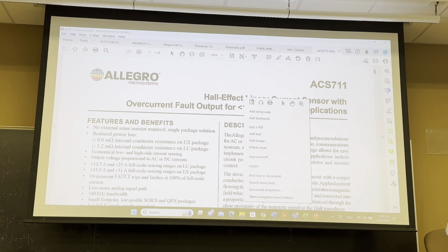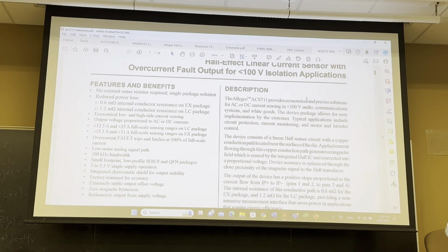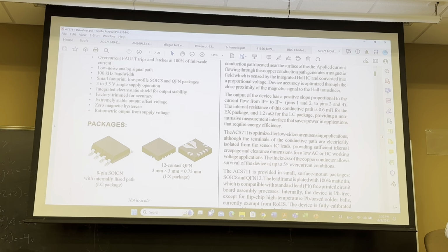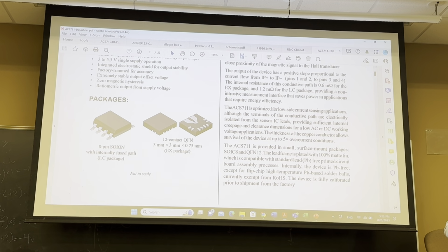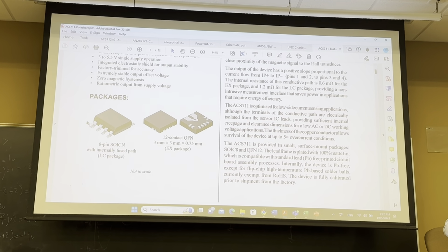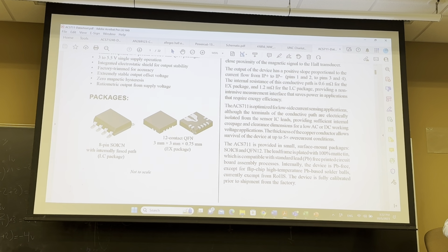So it's Hall effect, plus or minus 5%, doesn't matter, so we come here. Sometimes it says what the typical application is, and that may help you. It comes in two different packages, so now you want to see which one you want to use. This one is a SOIC package, so the pads that you need to provide are very different from this one. This one perhaps is better soldered in the oven, or you want to use a heat gun.